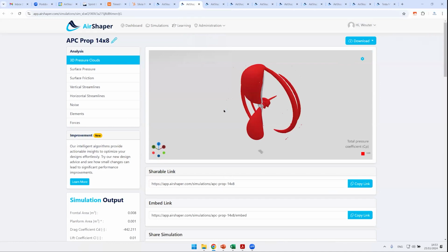Yes, just one question which is connected to that, and then we can answer it. So one is to get this 5% error, for example, in this very tight error. So what should be the typical mesh size, and what turbulence modeling approach do you use for this? Yeah. We use steady state simulations using K omega SST as a turbulence model. And in this case, we actually had a mesh of just 10 million cells.